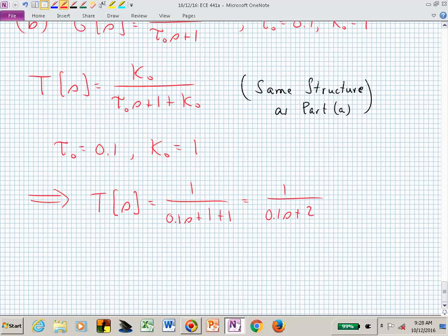What if we had 10 poles down there instead of 1? We would look at the dominant pole. Is everybody comfortable with the dominant pole? In this class, we'll just assume that that's the closest one to the origin. And if they're complex, now that we're looking at the hypotenuse, how far are we from the origin? We'll take the dominant one, or the dominant pair. They will play together as a whole, but if they're widely separated, the dominant pair are just the 1 or 2 that are closest to the origin.